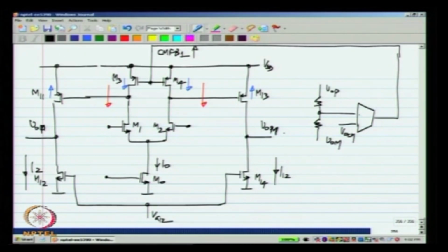So, we need a transconductance of that polarity over there, a transconductor or an amplifier, such that if VOP and VOM are too high, they should become small, and if VOP and VOM are too low, they should become larger. By the way, I should add the integrating capacitors here.